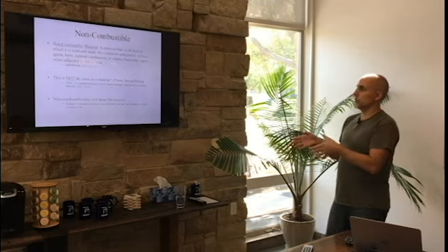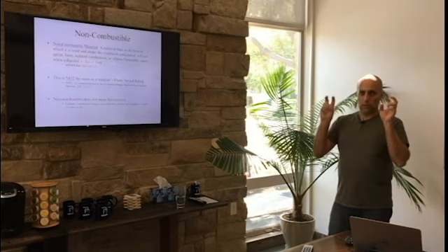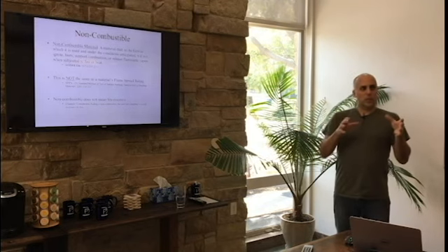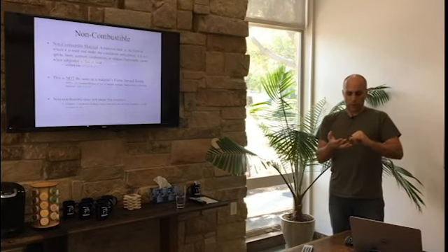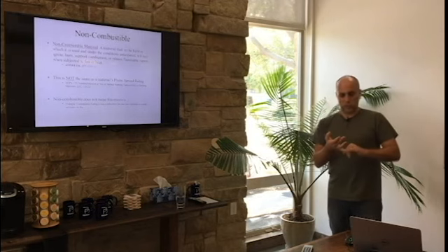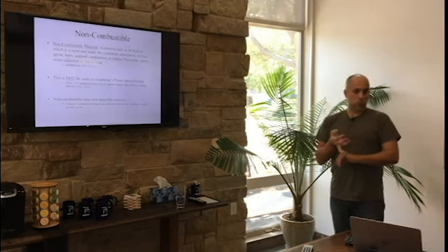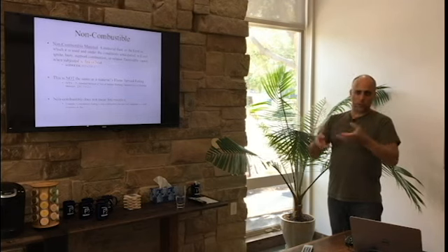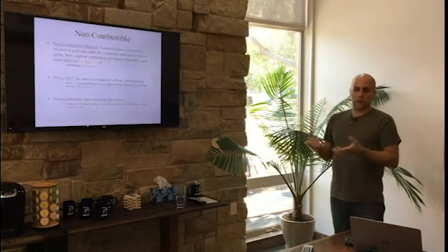Good example that I use all the time is Hardie Plank, that's the brand name, or cementitious fiber siding. It's made up of fiber, it's got some wood fibers in it, but it's Portland cement with reinforcing fibers. It doesn't burn. You can try burning it, it just blackens and doesn't burn. But it's not fire resistive.